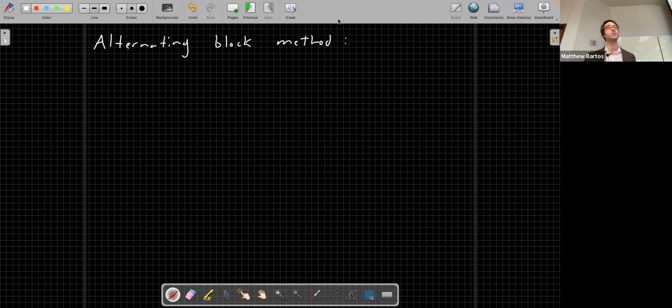This is used in many hydrologic models. You'll see this in HEC-HMS, and you'll see this in SWMM. It's a method of taking those IDF relationships and creating a realistic looking rainfall event out of them. If you go into the options in HEC-HMS and specify a rainfall event, often it will be in the form of the alternating block method.